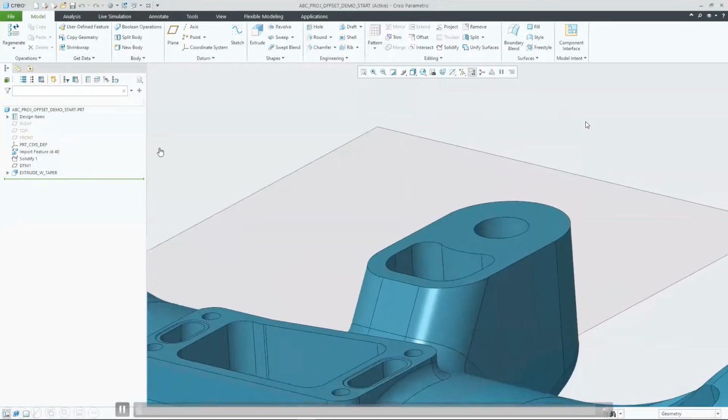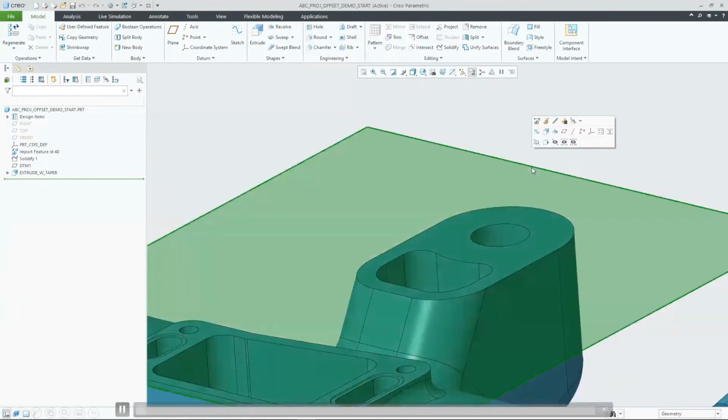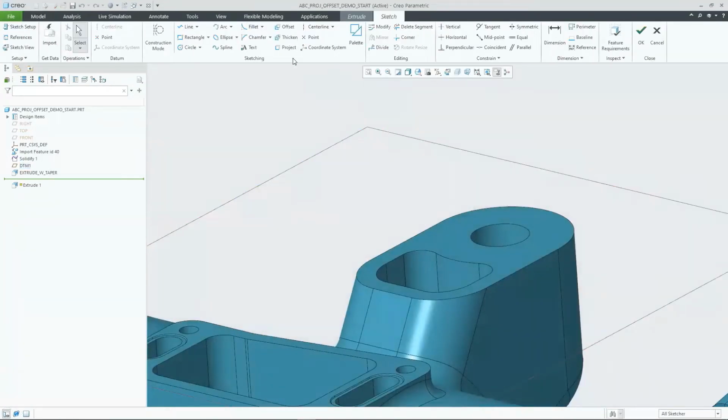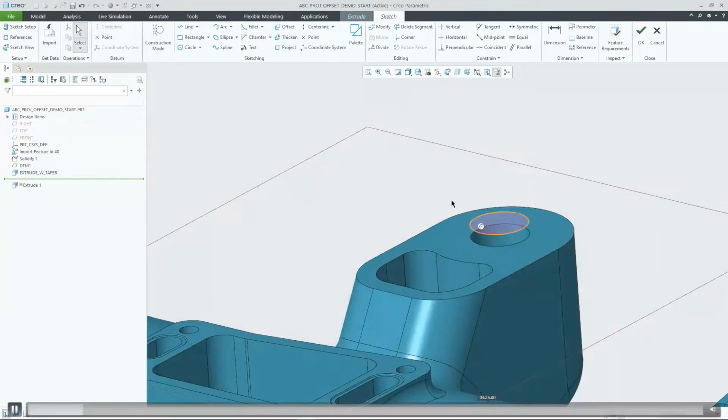Offset tools in the Sketcher environment are modernized in CREO Parametric 9.0. Both present themselves with a modernized tool UI, modernized workflows, and modernized reference handling. When invoking the project tool, you see the new tool user interface with the chain collector activated, allowing you to select edges in the 3D model and project them into the sketch.